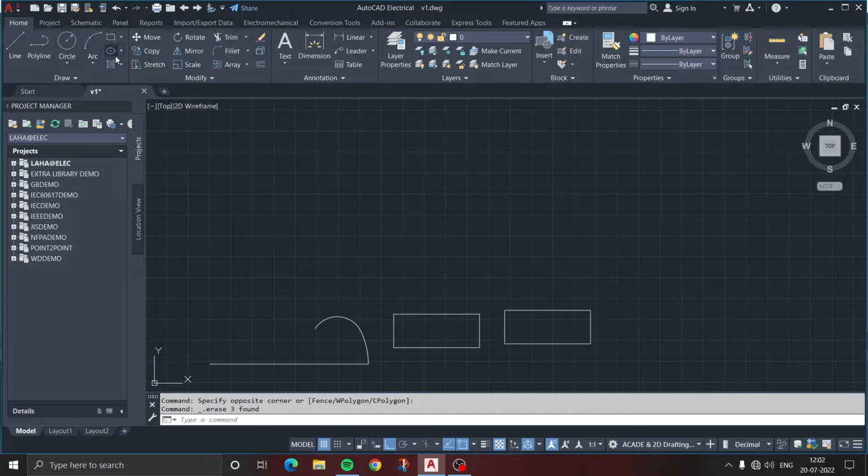Well, the next option you can see, that is ellipse. To draw an ellipse, first of all you have to know the length of major axis and minor axis. Well, I am going to draw a major axis. Okay, you can see ortho mode is on. Now you have to specify the length of the major axis, say 80 units.